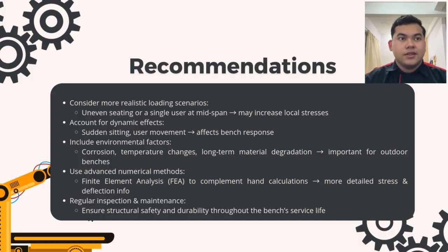so further studies should consider this scenario to ensure safety under all conditions. Number 2, account for dynamic effects. People don't always sit gently; they might sit suddenly, shift or move on the bench. This dynamic action can produce short-term forces higher than static weight, affecting stress and deflection. Including dynamic loads in future analysis will give a more accurate picture of bench performance.